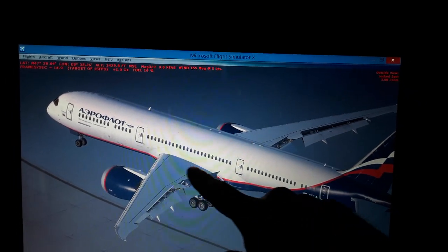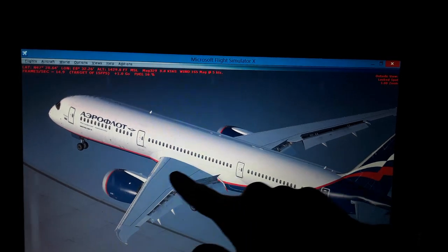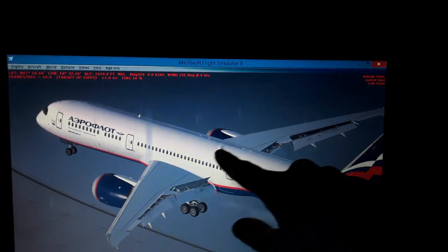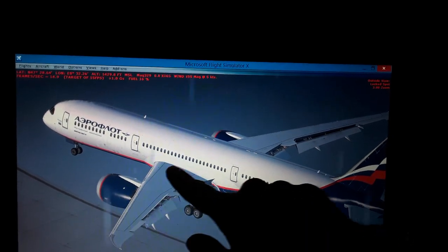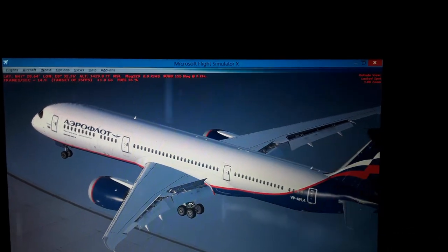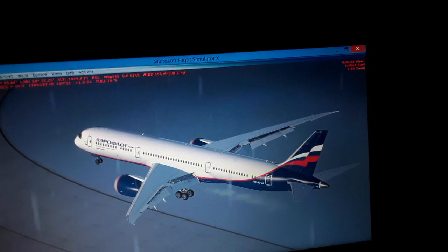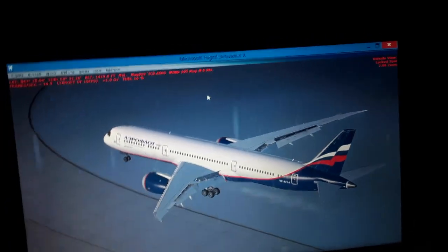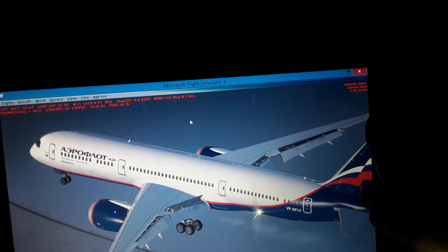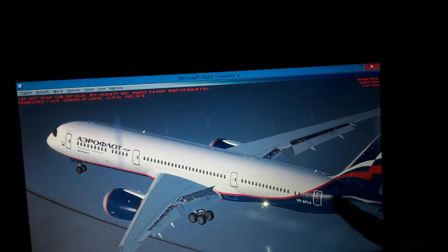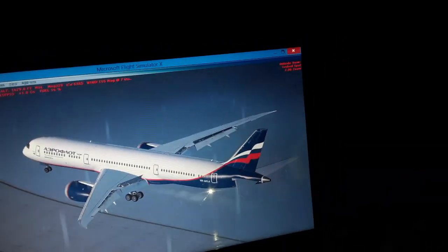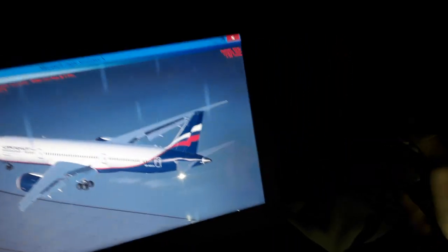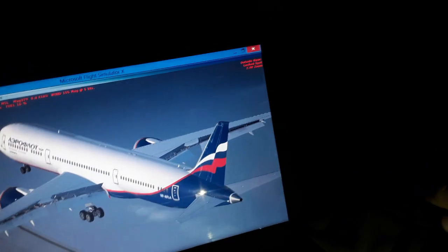So the airflow, we have the mean aerodynamic chord position, about 23% of the max, pretty much here, where the maximum aerodynamic lift occurs in the forward wings, where the stall also will begin on the top surface of the wing, so we need to avoid the stall. We have the axes here, the lateral axis from wingtip to wingtip and the longitudinal from nose to tail. That affects also the horizontal trim stabilizer over here, as I told you, the horizontal tail, so we can trim the horizontal tail, as you can see, for climb and descent like this.